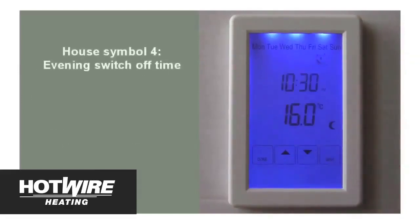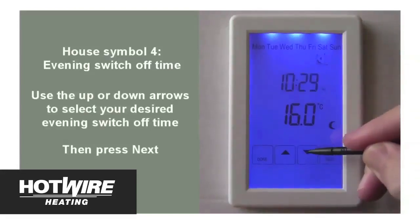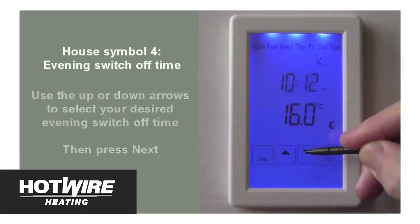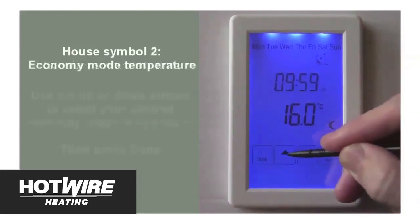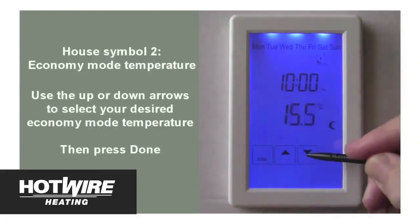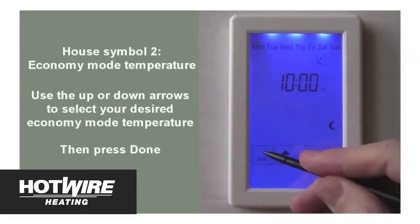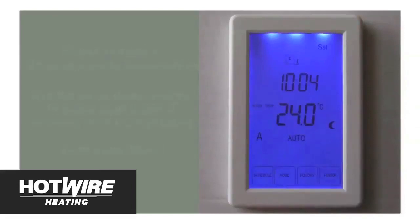The house symbol displaying the number 4 with a person inside will show at the top of the display. This is your floor's final switch off time for the night. Select your desired switch off time, in this case 10 o'clock at night, and press Next. Then select your desired minimum or economy temperature for the night. In this case we will choose 14 degrees. Then press Done. All of the days of the week have now been set with those switch on and switch off times.